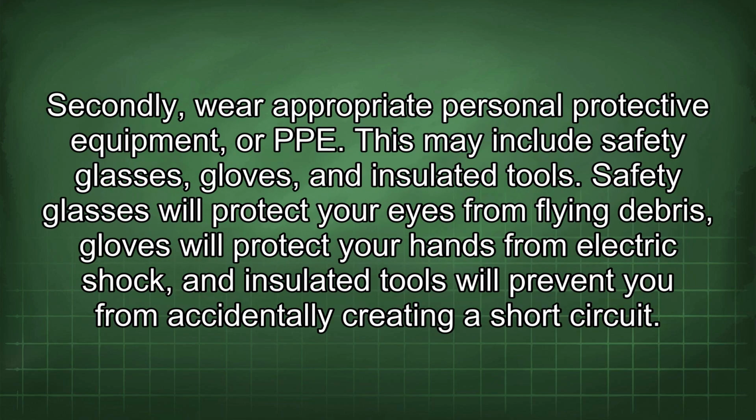Secondly, wear appropriate personal protective equipment, or PPE. This may include safety glasses, gloves, and insulated tools. Safety glasses will protect your eyes from flying debris, gloves will protect your hands from electric shock, and insulated tools will prevent you from accidentally creating a short circuit.